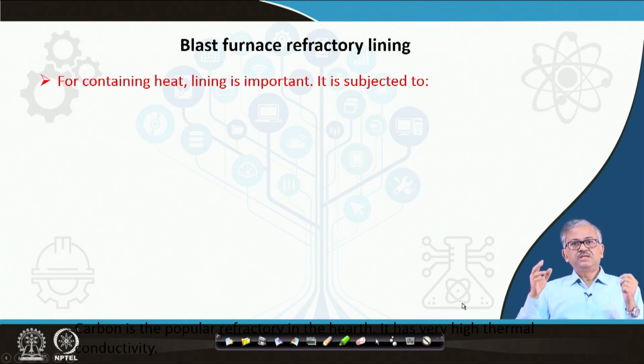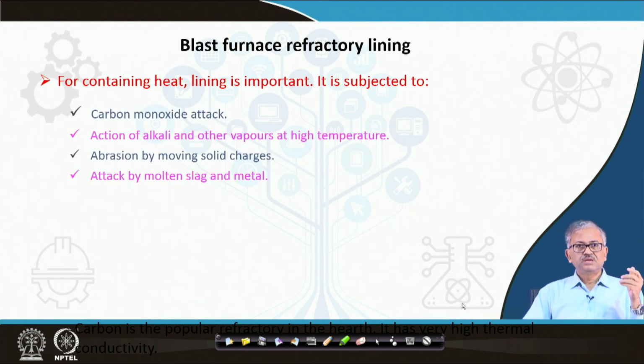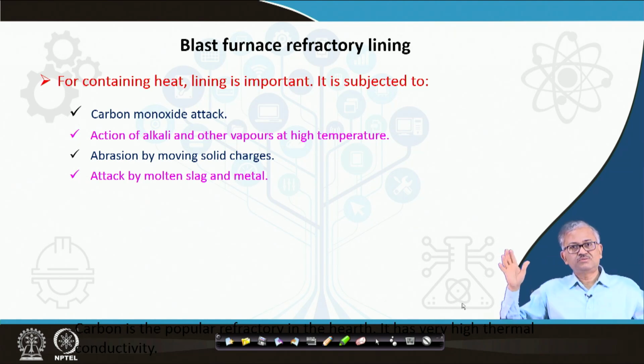Basically, the main purpose of refractory brick is containing the heat. Besides, refractory brick also has other purposes. It must withstand carbon monoxide attack, action of alkali vapors at high temperature, abrasion by moving solid charge, and attack by molten slag and metal. These are what the refractory is subjected to, and this is its function, but another function is containing the heat, such that you don't allow the heat to go away.